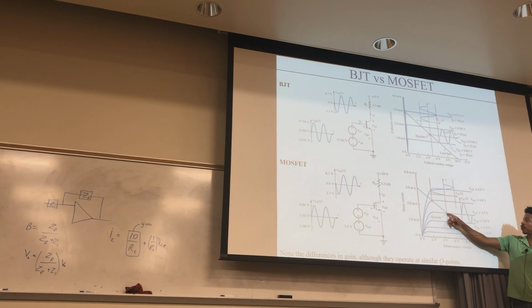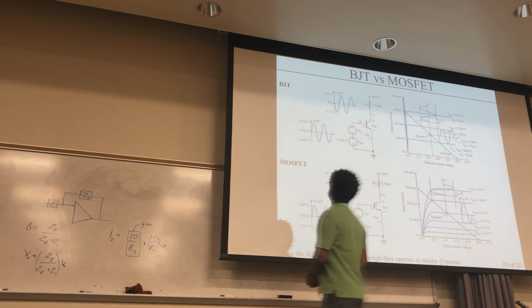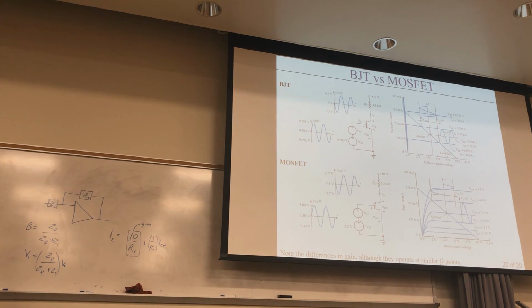But if you know where your Q point is, you'll set that value at your 3.5 line, and then you go up and down your peak values right here. Then you're able to get some kind of picture of your output. Good question though.